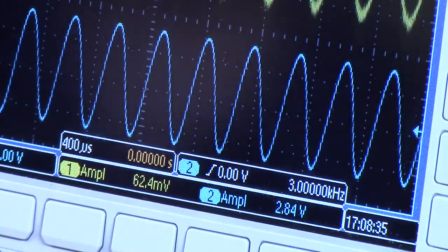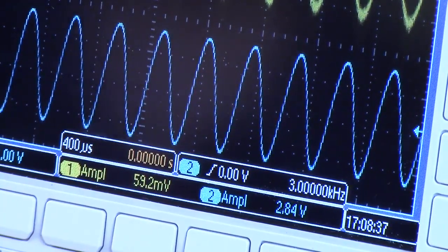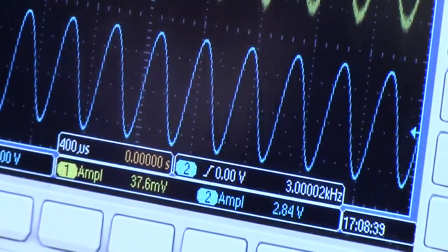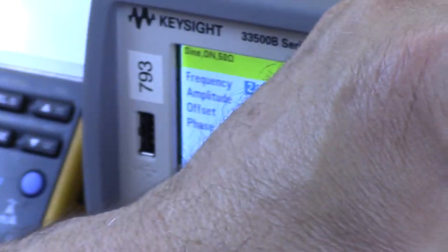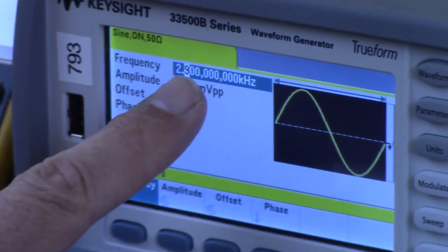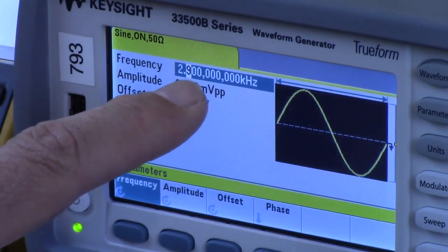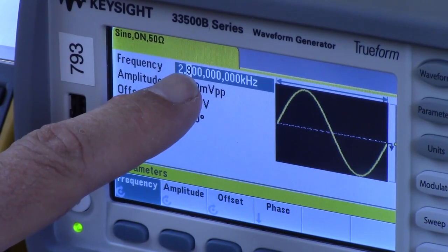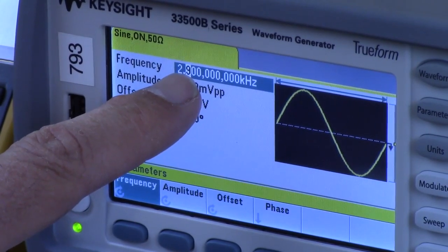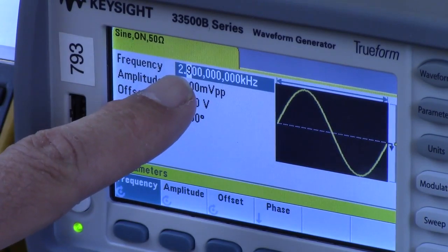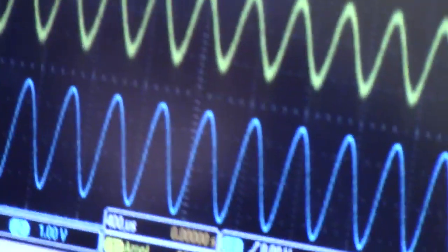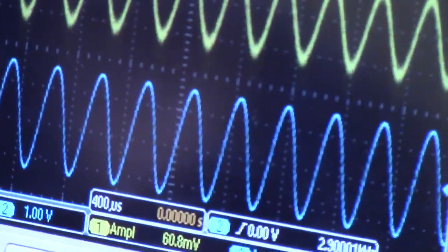We're pretty much there. So what this tells us is that the pole due to CE is at 2.9 kilohertz. The thing to keep in mind was that when we did this lab in the very beginning and we ran that signal at 1 kilohertz, 1 kilohertz was not really midband condition. You have to get above 4 or 5 kilohertz to get to that.